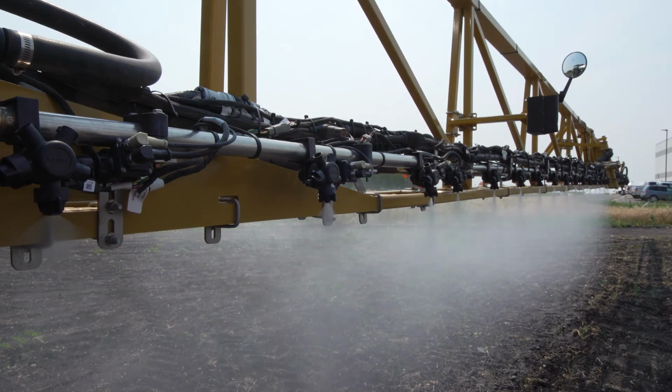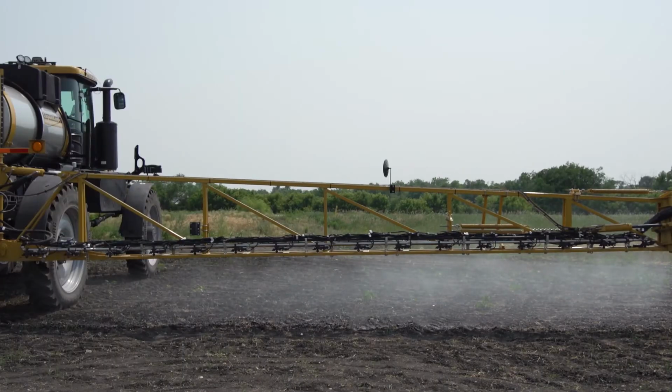It also could be that, by golly, I forgot to change the nozzle tip, and now I've got extra flow coming out of this one because I put the wrong tip on there. Whatever the reason, we've got more flow coming out of this nozzle. Both the spray patterns are unaffected. On the low flow, that could have been for a number of reasons as well. Maybe I have the wrong spray tip, but I also might have a pre-nozzle filter that's plugged up with some gunky material or whatever. That could be causing that low flow. So let's scan the spray. Can you see which one's low, and can you see which one is high?